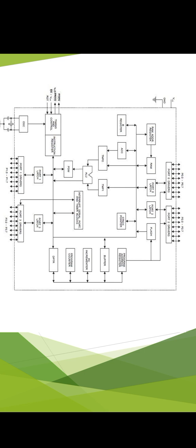In register bank 0, the address is 00H to 07H. H is hexa. If register bank is 1, the address is 08H to 0FH. If register bank is 2, it means 10H to 17H. If the register bank is 3, it means 18H to 1FH. Finally, the special function registers. In the SFR area, the address ranges from 80H to FFH.